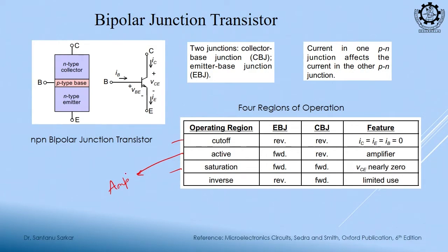Okay. So, in this analog class we are interested in this zone, which zone? Active region. And this other zone, inverse active, is not that important. So, mainly we will be thinking about the emitter base junction as forward biased and the collector base junction as reverse biased. If this is forward biased, the base voltage should be at least how much above the emitter? 0.5 to 0.7, right. If it is above the emitter voltage, we will consider this forward biased, and this is N, this is P.